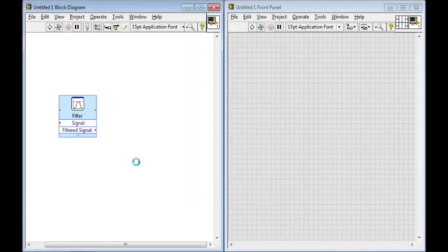The reason why we need a filter is that every time you hit run, the moving average starts at 0, and then the average changes based on the input of the DAC to a new point. So you're going to have a transient regime where it's not the actual value that you're getting in. You have to run it continuously over a few seconds to wait for it to respond and get to the right level. Once it's finished responding, you'll get basically a flat graph of what value it is. And that's what we want.